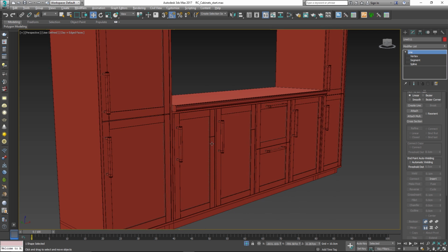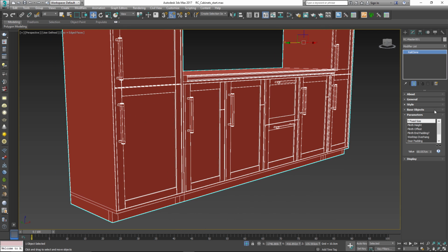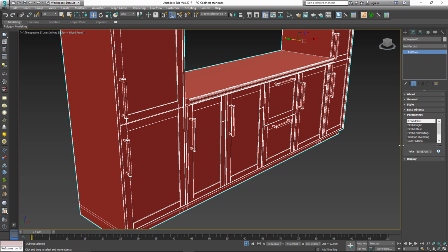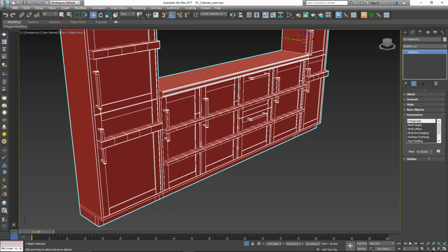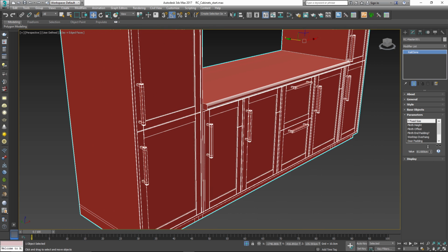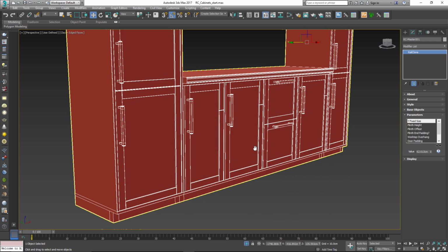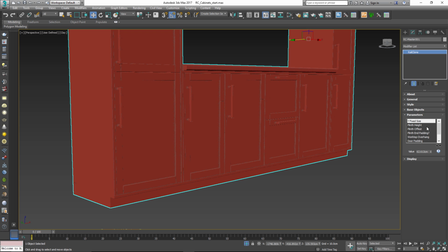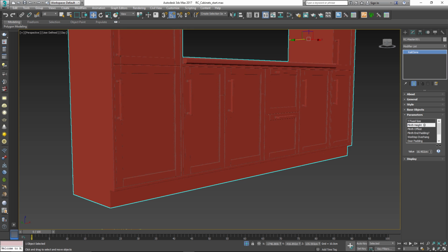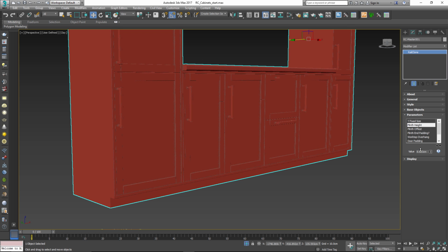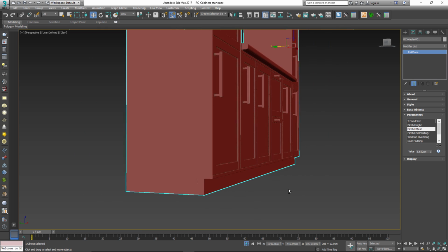but there are also a number of useful parameters found in the modify panel. The first of these is the Y size parameter that's used to adjust the depth of the cupboards. Everything is linked to this, so when it's changed it affects the cupboards, door position, plinths and cabinets. The height of the plinth can also be adjusted independently using the plinth height parameter. As you can see, when this is adjusted, everything above is also moved.